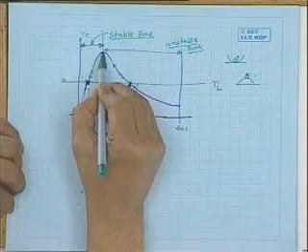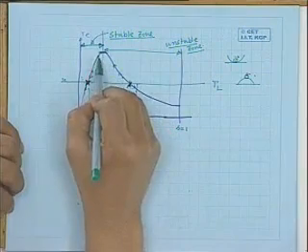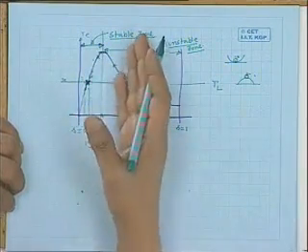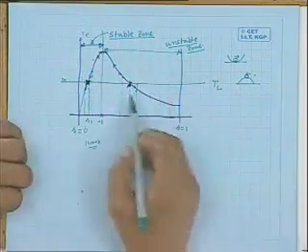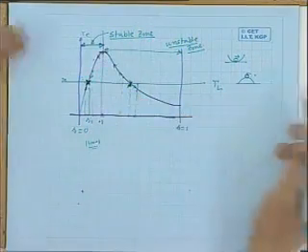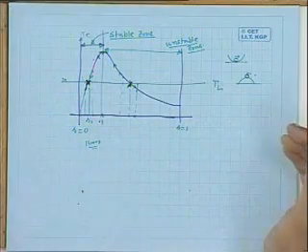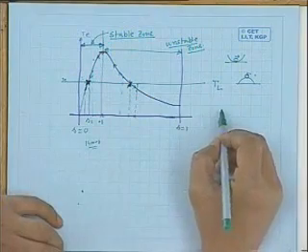So the slip of the induction motor in its normal operation should therefore vary from, say, 0 in the absolute no load condition to about 10%. But as I told you, this induction motor should not be operated very close to this point. Although it is stable on this side, it is as if approaching what is called the line of division between stable and unstable, and if it crosses this point, everything goes, meaning the machine comes to a stop like that.